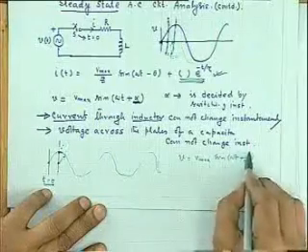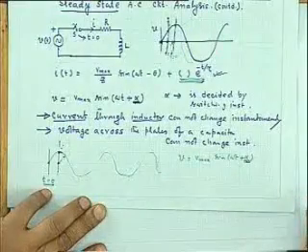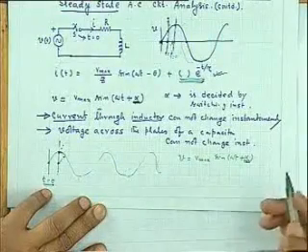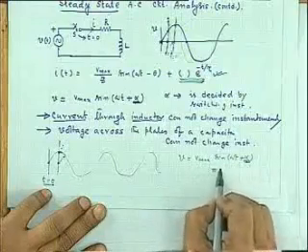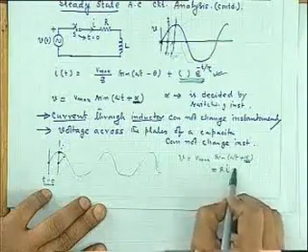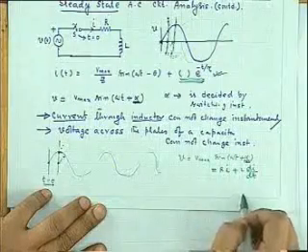If alpha equal to 90 degree, I have closed the switch when voltage is maximum, like that. So with this voltage present as a general case, where alpha could be anything between 0 to 2 pi, you really do not know. One can do a little bit of research on this. This is the voltage and I want to find out the current. So I will write down Ri plus L di dt.